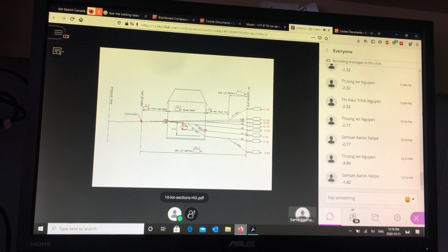You could be higher than 2.56, then you know you have a front draining lot with a full slope and a little bit of a wall. You could be lower at the back by more than 4 meters, and then you know you have a full walkout with a minimum usable backyard, a full 3-to-1 slope, and then a retaining wall. Or you could be somewhere in between as a scenario.